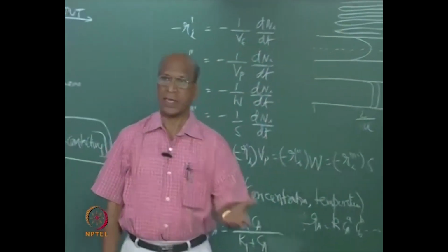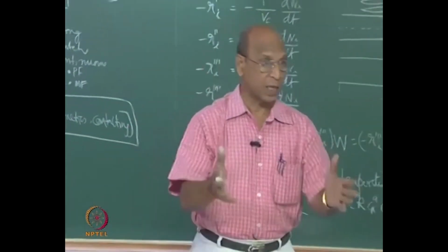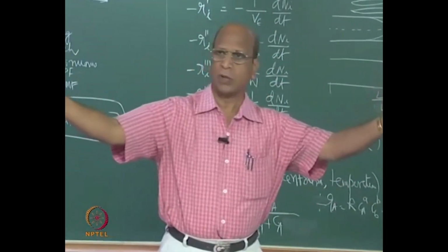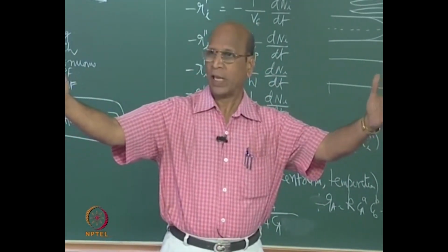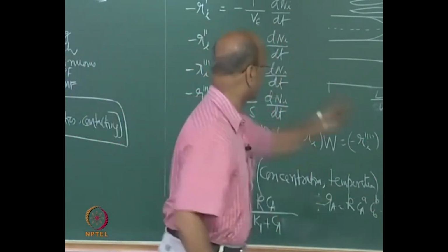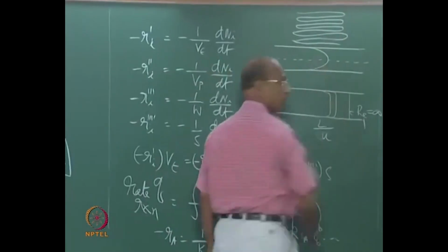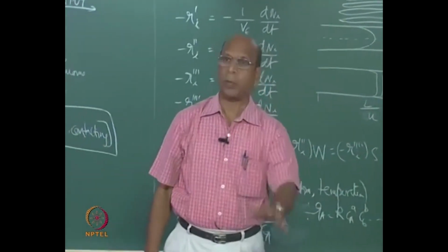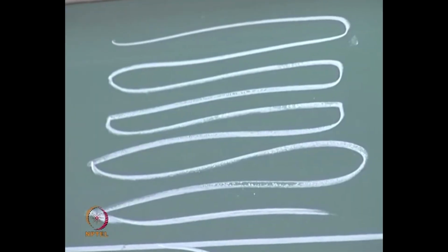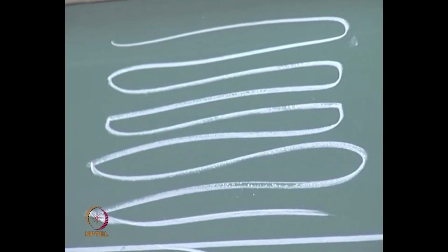And you know, sometimes in industry you will have 2 kilometers, 3 kilometers length of plug flow. That means like this many, each one will have 30 feet or 40 feet length. Like that you can now count how many numbers you have to put and then join at these ends, and you can guarantee that there will not be a plug flow, even though we say that it is plug flow reactor. That is why you have non-ideality coming there.